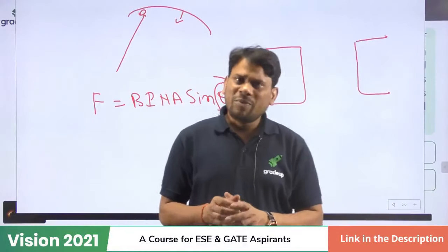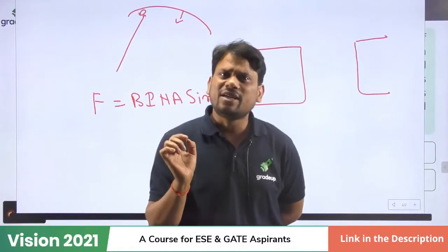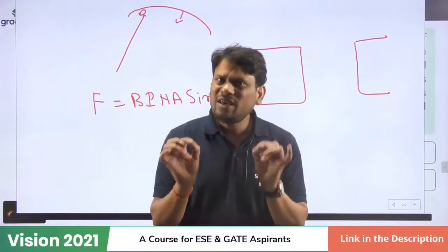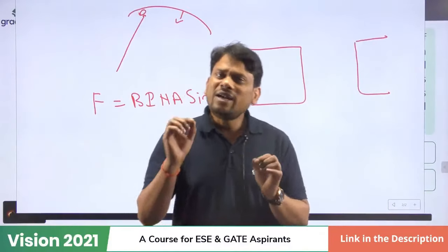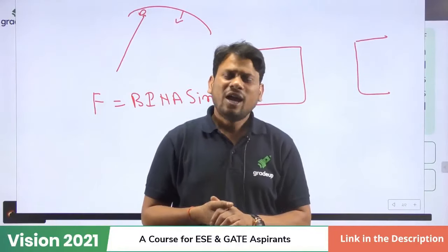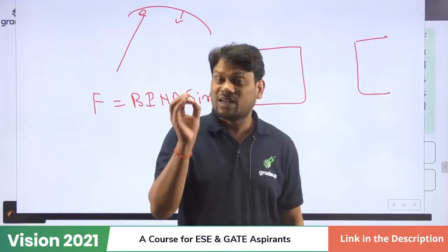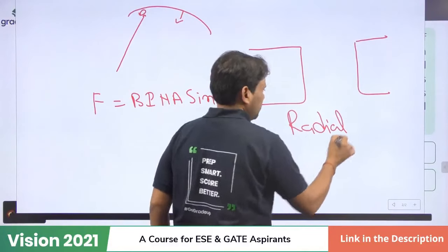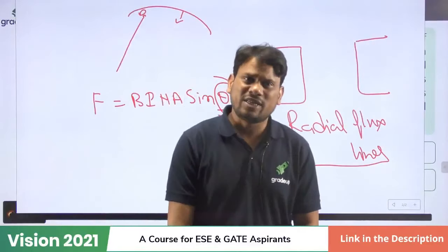Okay, listen to me carefully, dear friend. If theta is not equal to 90 degree, our PMMC will introduce high error. PMMC is nothing but a kind of galvanometer. Please mind it, a kind of galvanometer. And a galvanometer provides a full deflection when theta is 90 degree. To make theta equal to 90 degree, we require radial flux lines. Please mind it. That is the most important thing.